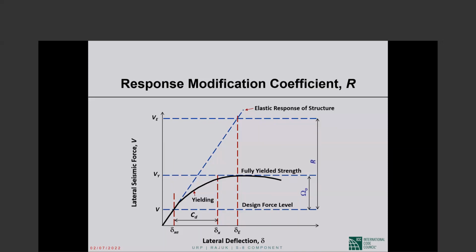If we want to figure out the largest bending moment that can be developed at this section, if the design earthquake were actually to hit, our estimate of that maximum moment would be omega sub 0 times the 100 foot kips negative.